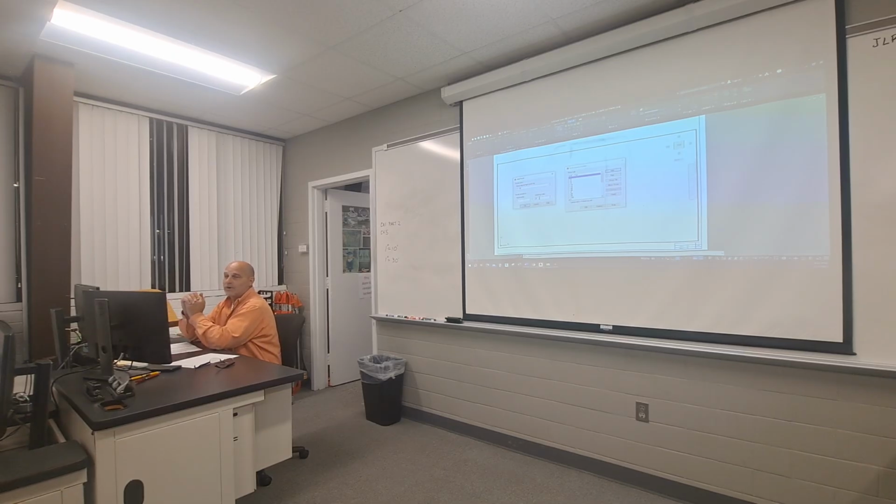Nowadays, we don't have to with AutoCAD. As long as we manage our viewport and do our stuff correctly, it's a fail-safe. And doing it correctly is just like you would do it out in the industry. So for this, to set up these new scales, we do have to put in that scale factor. So where it says drawing units, I'm gonna type the number that is there.